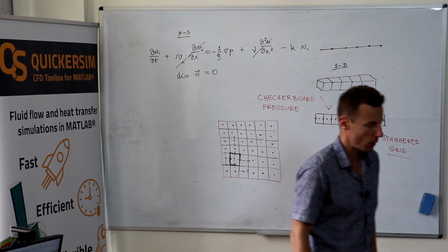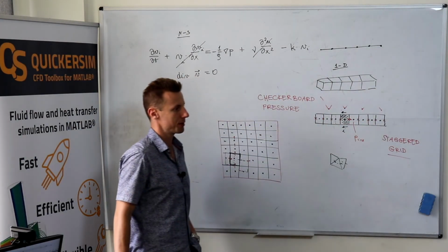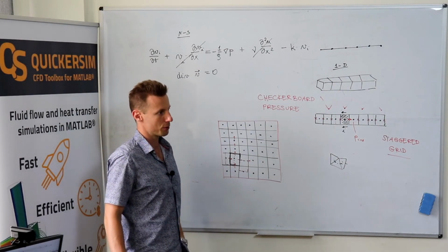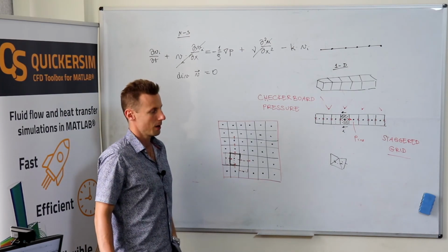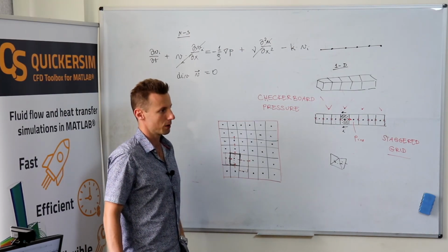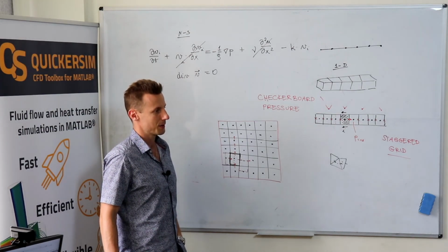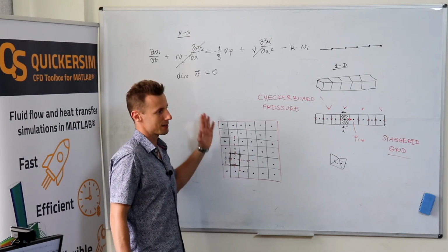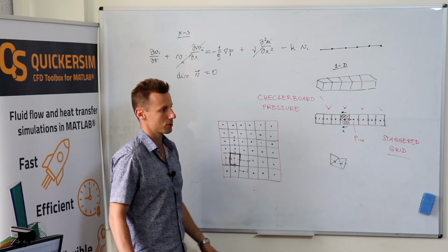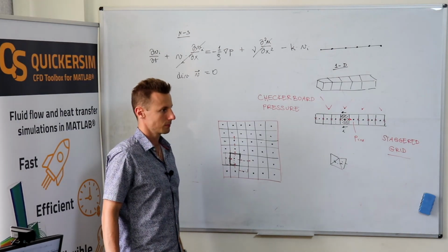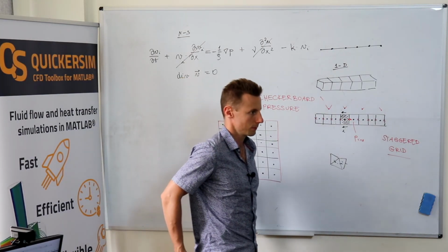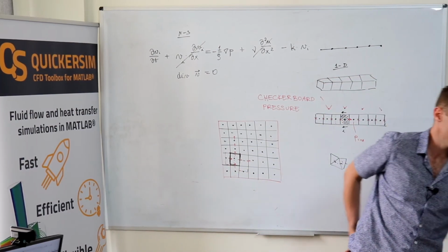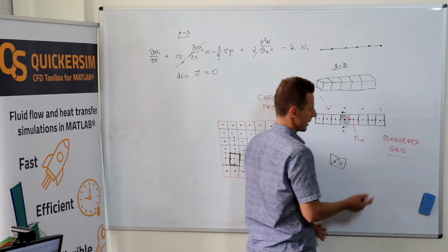No, I don't think the commercial codes use the staggered grid approach, simply because commercial or general purpose codes are implemented to work on unstructured meshes. And even if you import a structured mesh, it's still handled as an unstructured mesh. Yeah, but as far as I remember, CFX is working on a staggered approach, or I don't know the details of CFX.